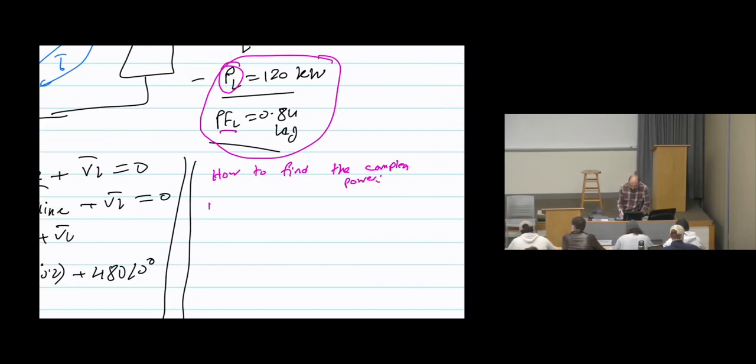Let's assume scenario 1, that the power is given as volt-ampere and power factor. That's one scenario, which is basically you already know S, and you can say theta equals plus or minus cosine inverse of power factor. Plus if it is lagging, minus if it is leading.